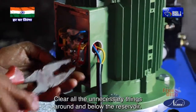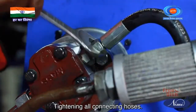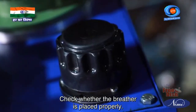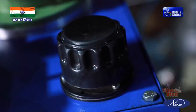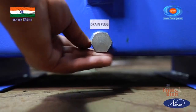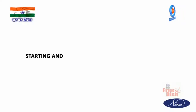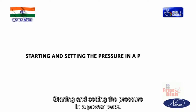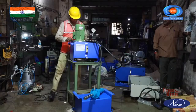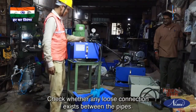Clear all the unnecessary things around and below the reservoir. Tighten all connecting hoses. Check whether the breather is placed properly. Check whether the oil drain hole is plugged and there is no oil leakage. Starting and setting the pressure in a power pack. Check whether any loose connection exists between the pipes.